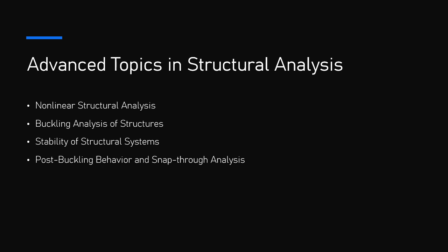3. P-delta effects. The P-delta effect refers to the additional moments and forces that develop in a structure as a result of its displacements under load. The vertical loads, P, acting on the structure create secondary moments as the structure displaces laterally, delta. This effect can lead to instability if the additional moments push the structure beyond its stable equilibrium. P-delta effects are especially important in tall buildings, towers, and frames under lateral loads like wind or seismic forces, as they can significantly reduce the stability of the structure.